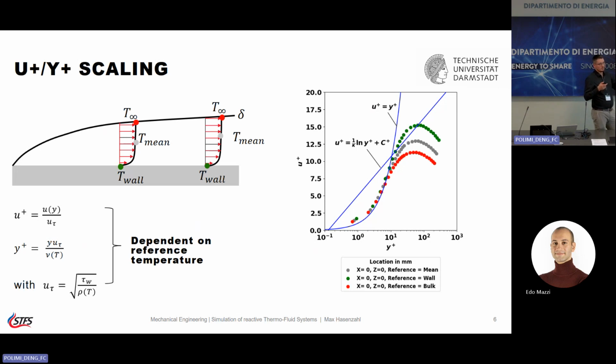So you can imagine if you take experimental data where they make some assumptions about the wall temperature, they make some assumptions about the bulk temperature, and then they scale their data. If you were just to compare to this, like you find in the literature, then you will get discrepancies just based on very small differences in the wall temperature. So what I elected to do was I took the data from CFD, so the thermophysical data, so the temperature profile from the CFD, and I scaled the velocity data from the experiment. So that's how we got the plots you just saw.